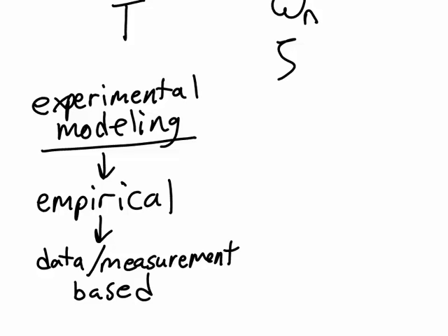In the second part of this class that we start today, we are going to begin looking at the mathematical underpinnings of systems. We are going to see exactly what, mathematically, makes a system either first order or second order. We will start to see how systems can be modeled mathematically and how parameters like the time constant, damping ratio, and natural frequency can be found or at least approximated without doing an experiment.